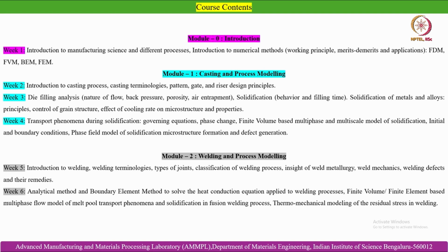And then we will also discuss the initial and boundary conditions of a typical finite volume model of solidification transport phenomena, and afterwards we will discuss the coupling of the CFD based solidification model with the phase field model, wherefrom we can also simulate microstructure formation of the solidifying parts, and also we can predict the different kinds of defects that generally get generated during solidification.